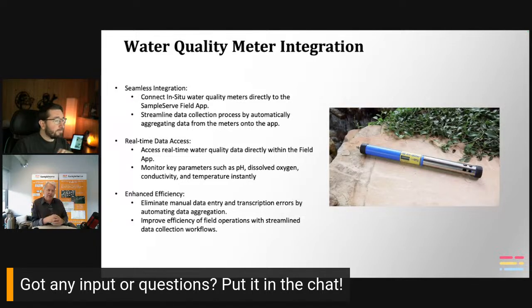Theoretically, the panacea of what it could be is where you get a system set up, a pump and a meter and everything going, hit the start button, and it starts reading. Once your groundwater level is stabilized according to your pumping rate, you can go to another location and set up another set of equipment, and potentially be sampling 2 monitoring wells at the same time.